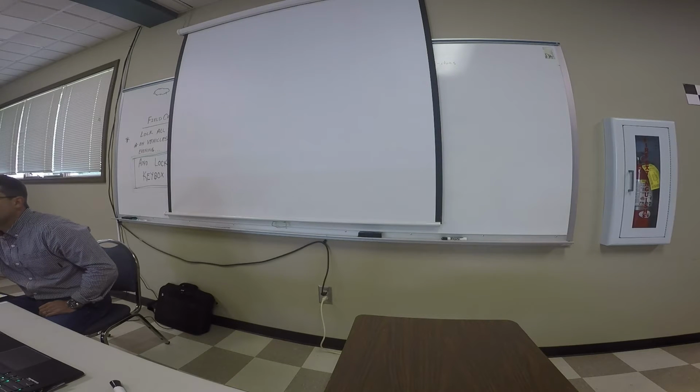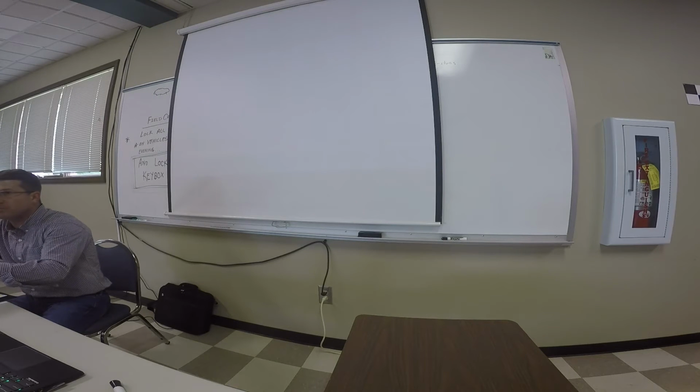Did you say a sign? If you just say SN, it will draw a line? SN is always going to draw lines for our field to finish. If you put SN1 and you shoot a big monument sign for a Kroger, and you shoot SN1, and you shoot that next corner, and then we always alleviate the 4th corner because we know it's going to be a rectangle. 4, enter, bam, it makes it square in our AutoCAD. So there's no use for you taking that extra shot.